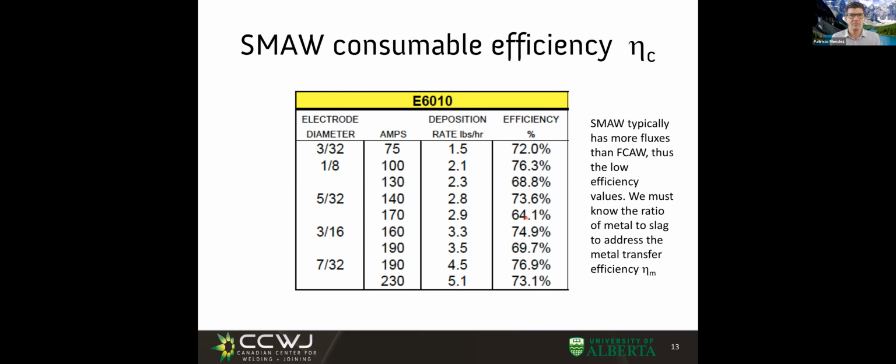Not always do we need it. We already discussed that for most welds, you just go and weld and the world is good. And when it gets difficult, you get the Procedure Handbook of Arc Welding, and then you become better than 90% of engineers, maybe more. When things get difficult, you know exactly what to do. And this is universal for all alloys. So if you ever have to weld tantalum, you might not have this tabulated data, but you'll know what factors are at play.